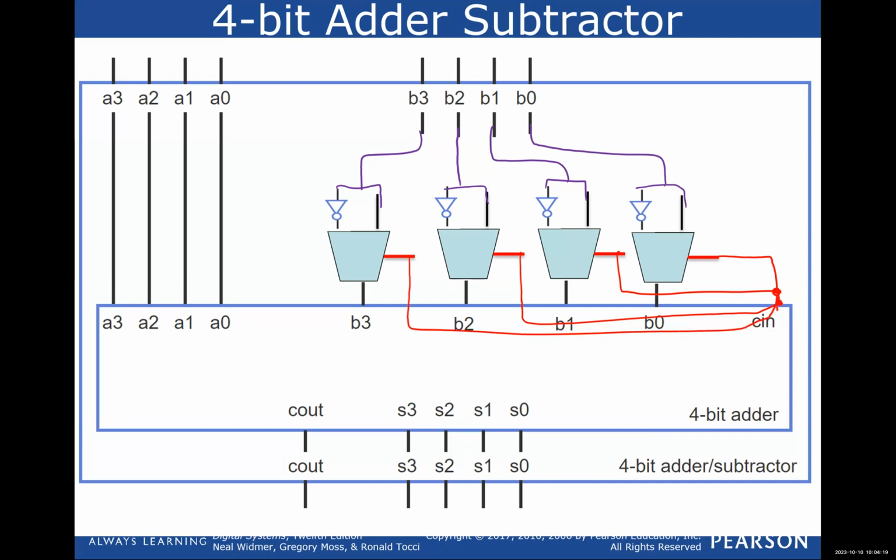Now, how does this work? Okay, if I say A plus B, let's do this. If I say A plus B, we said that for the selector C input, if I choose C input to be 0, so that means that you have a switch there on your FPGA board. You're going to make that switch 0. If you make the switch 0, you know that the two numbers you're putting in there, an addition operation is going to happen between them. Okay. If you make the switch go to 1, you know that the two numbers you put there, the operation that's going to happen between them is going to be a subtraction operation.